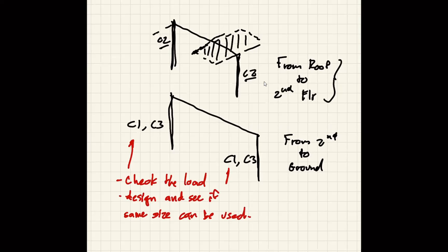Okay, generally before we engineers design the sizes of the members, we would look at the load and try to group the load. For example, there must have been a good reason that they use the same name on both sides, because you have done the analysis. I haven't looked at your results, but if the loads are not too different, you say, okay, the loads are pretty much the same, so I'm just going to pick the most critical one, which is going to be only slightly more than the other one, and then design my column for that.